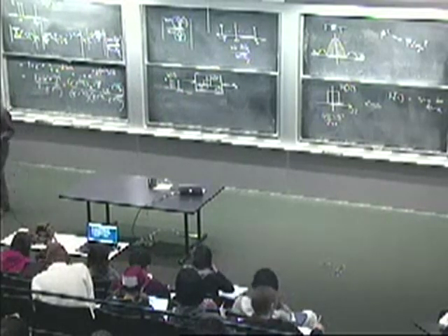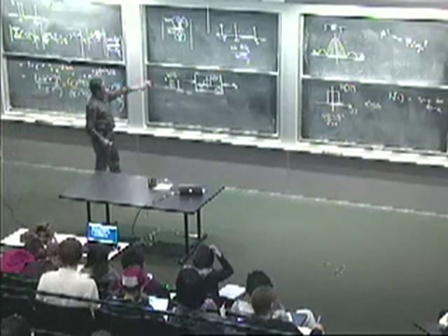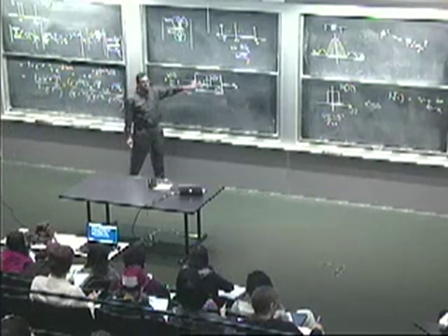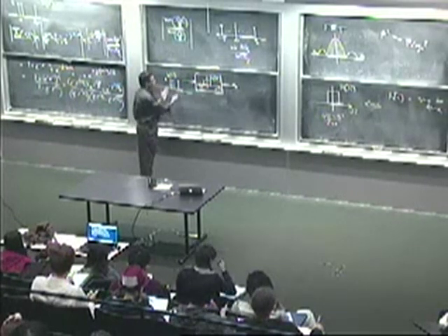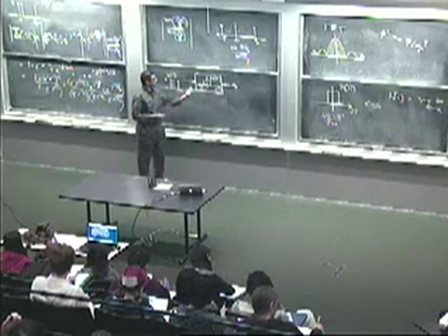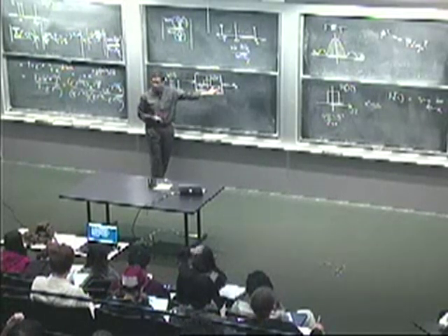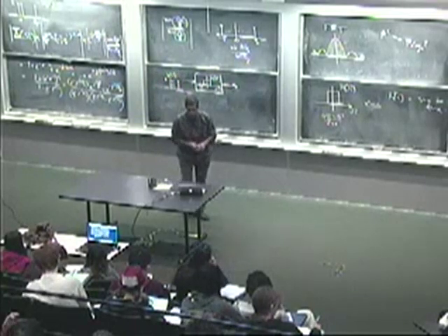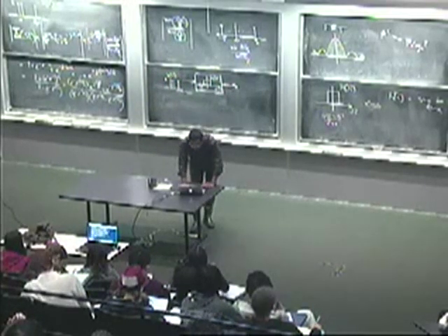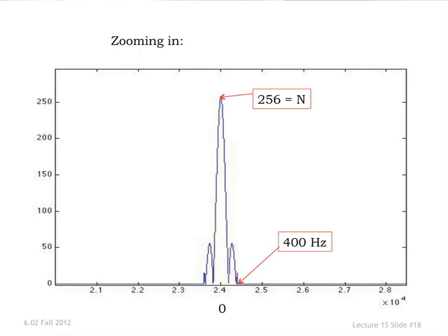So if I'm thinking of it in the frequency domain, then I take the spectral content of the signal, which we've just worked out, and multiply it by the frequency response characteristic, which just basically selects out the frequency content that's in the passband and rejects everything else. Then that gives me the spectral content of the output, and I can translate that back to what happens in the time domain. So here, let's take a zoomed-in version.